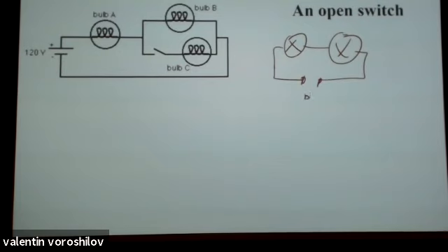So the voltage, resistance 1, resistance 2, electric current travels from plus to minus, so electric current in this circuit travels clockwise. Electric current through each bulb travels to the right, and this electric current I will be equal to voltage over the total resistance, R plus R, 2R.